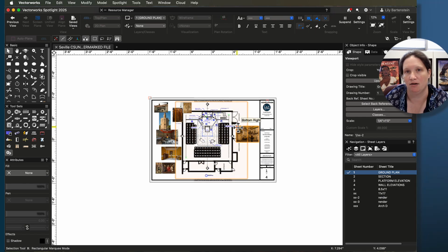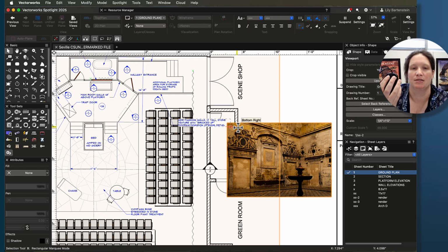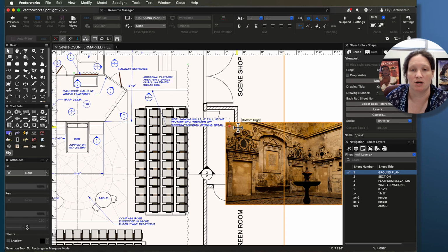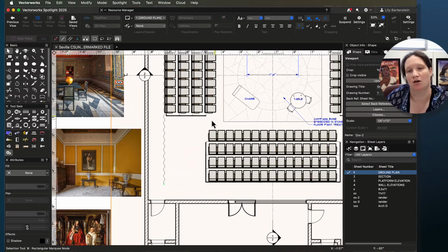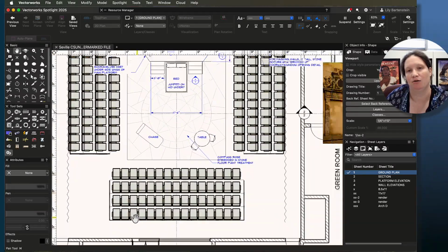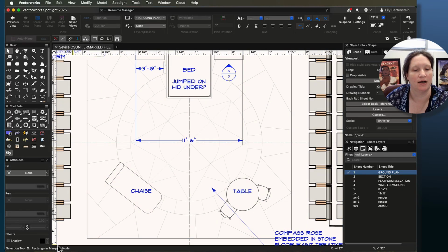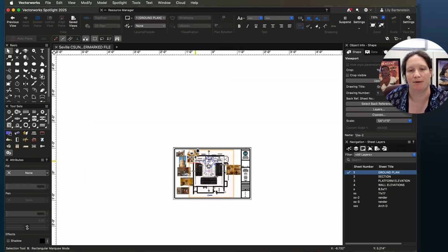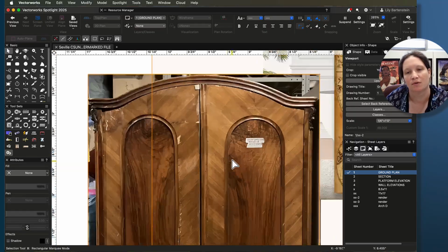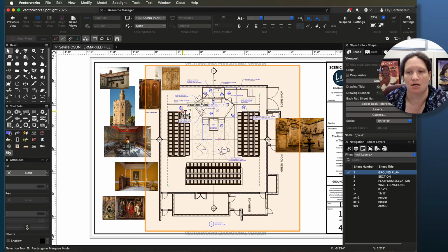You'll notice I'm zooming in and out. I am using the scroll wheel on the mouse, right? Another important tip with this is, if I've zoomed into this point and now I want to move around, I'm going to click and hold on the scroll wheel. My cursor turns into the hand tool temporarily, letting me move the drawing by clicking and dragging with the scroll wheel, so that I'm able to make my way around the drawing without having to go find scrolling and figure out how to get wherever I'm supposed to be, or having to zoom out, point my mouse at the thing I want, and zoom in. Okay? Terrifying dead bodies and body parts. Cool. So that is a navigation tip, right?